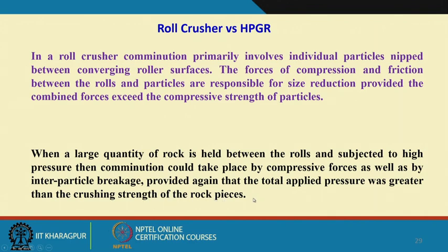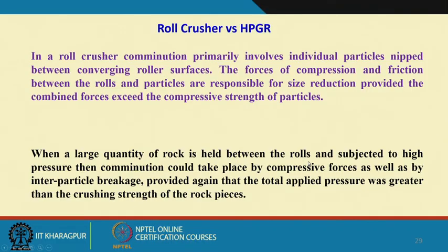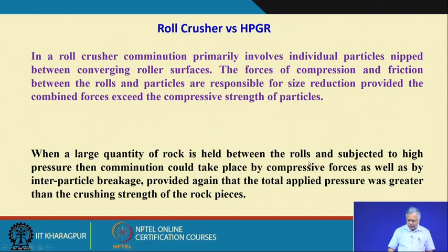So, there is a fundamental difference between these two: when a large quantity of rock is held between the rolls, which is what we are doing in an HPGR, and subjected to high pressure, then comminution could take place by compressive forces as well as by interparticle breakage.